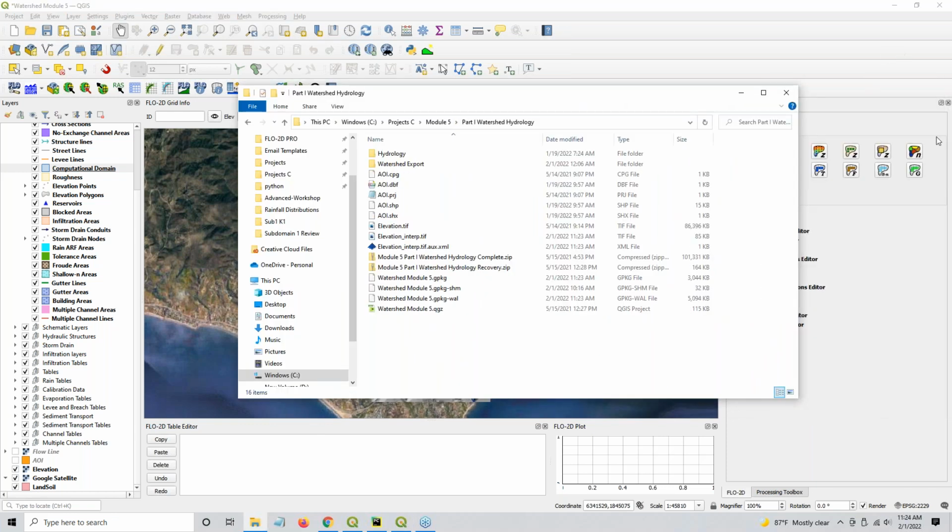And the reason we use the no data value of -9999 is because when you create a warp with the GDAL warp tool, what it does is it builds a new elevation raster for you that is perfectly aligned to your grid and has the same pixel size as your grid element size. So that's how we interpolate the elevation from this high resolution raster into this low resolution raster. And then we just sample this raster at the centroid of every grid to get the grid element elevation. So that's why you need that -9999. It applies to this raster.